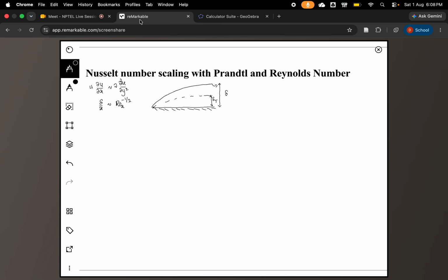So both the boundary layers can be of different sizes. And this is happening because, as I said before, this is about how the gradients propagate. This is how far the influence of this wall has reached into the free stream. For velocity, it is about the viscous dissipation. For the thermal case, it will depend on the thermal diffusivity alpha, which depends on thermal conductivity. So we will see that as well.